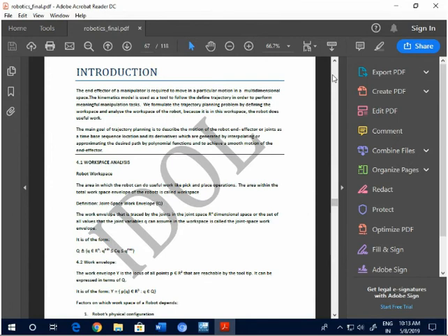Okay, so transform raised to the tool by the base. We used to solve direct kinematics using the DH algorithm, and in inverse kinematics we found a set of variables which will satisfy the same position and orientation.